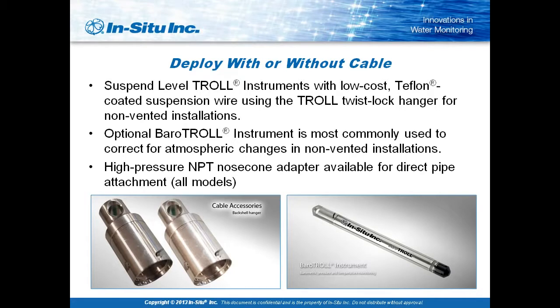So normally, you will change the desiccant out depending on the size and depending on where you are. If you're in Wyoming, it's going to be a little different than if you're in Louisiana. But in any case, those desiccant chambers are normally good for 3 to 6 months. So you do need to incorporate that into your thinking and into your project costs. If you don't use desiccant, you will end up compromising the piece of equipment. So always use desiccant and keep it fresh.